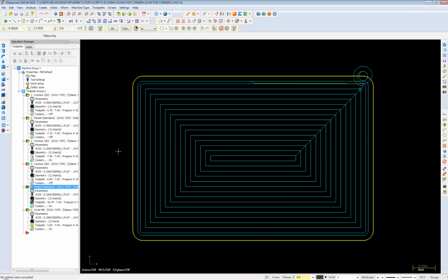The Pro E has a thing called flavors. On their IGES output, when the flavor settings are set just right, it'll be one of the cleanest IGES files you'll ever get. But if it's not, you start getting issues like you're talking about, including missing surfaces. And it's now called Creo, by the way. Right.